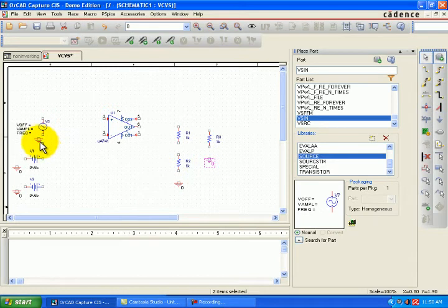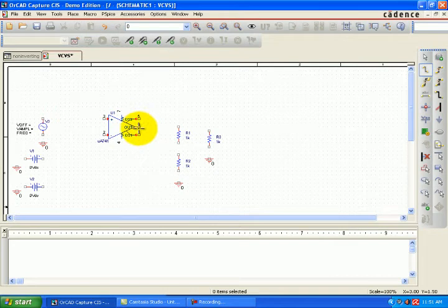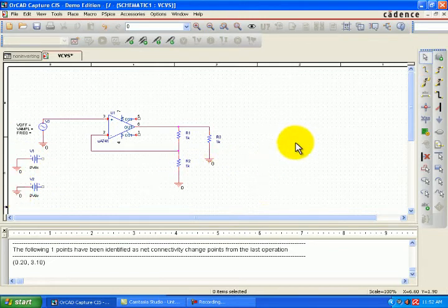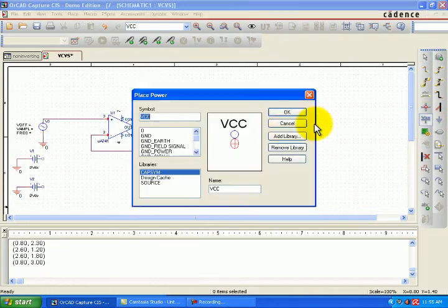Add the groundings to the input sources and the source to the IC. Connect all the circuits. This one is the R load. The negative terminal is connected to the feedback. 10% of the output is negative fed back to the input. Now this one is the source connected to the positive terminal. Connect the ground to the 15 volt DC supply to the IC.